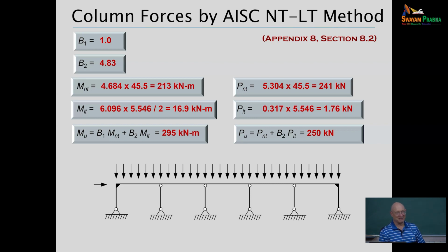You can see that it's very sensitive. The frame with nominal stiffness had an amplification of about 2.7. But once we reduced the stiffness by 20%, it jumps up to 4.8, right? Which means it's stability critical. Things are starting to get very sensitive to little things.